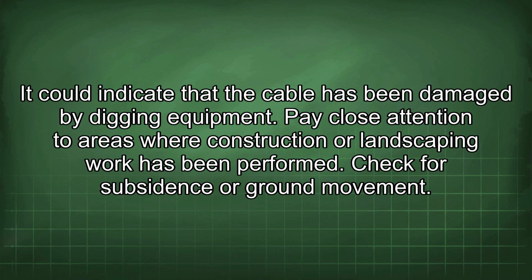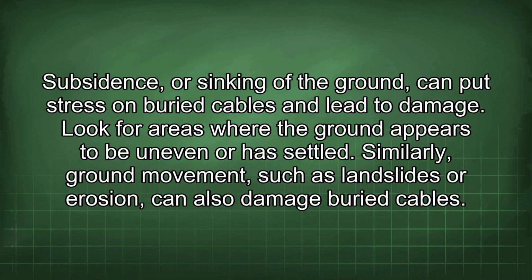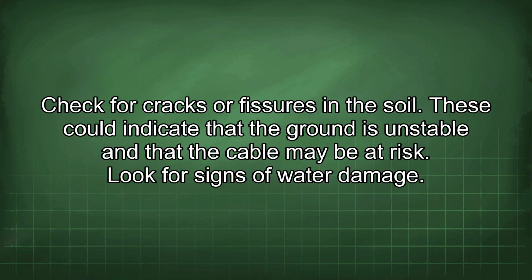Check for subsidence or ground movement. Subsidence, or sinking of the ground, can put stress on buried cables and lead to damage. Look for areas where the ground appears to be uneven or has settled. Similarly, ground movement, such as landslides or erosion, can also damage buried cables. Check for cracks or fissures in the soil. These could indicate that the ground is unstable and that the cable may be at risk.